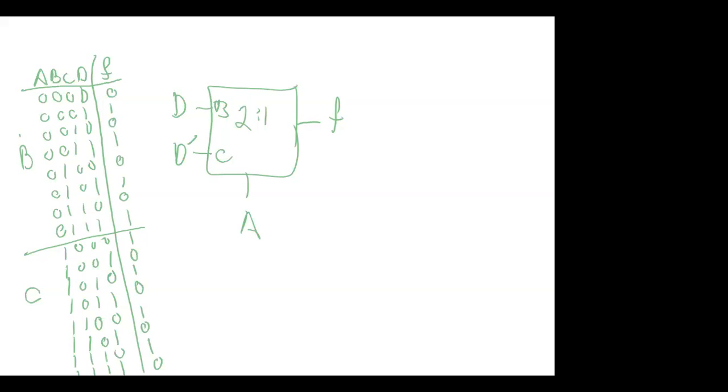We derived the truth table from our little, how you say, 2-to-1 multiplexer setup. Isn't that cool? So your 2-to-1 multiplexer has just implemented a 4-variable truth table, and you didn't need a Kmap for that.